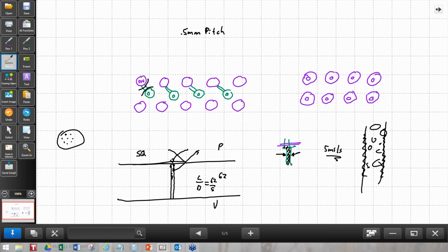So filling it with silver is great because it indeed increases the thermal conductivity, which is usually the problem, and increases the electrical conductivity, which is sometimes a problem. So plugging with a conductive material is great if you can do it, but in this particular case, it's very, very difficult. So oftentimes they'll just plug it with an epoxy after they plate it. If the length to diameter ratio is greater than about 12 now, you probably are going to have a special process done. It used to be 8 to 1 was a normal process, and most houses could do that.